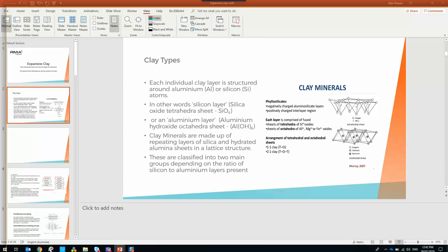For the guys in the built environment team, you'll realise we've got some standard designs that you can use. Instead of doing a full analysis on these, we just do a 3 to 3.5 metre grid of piers and just read off the standard tables.